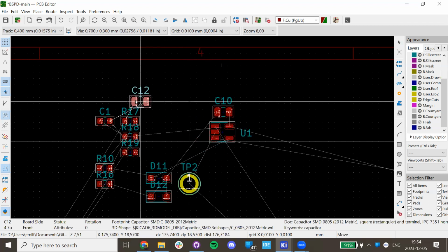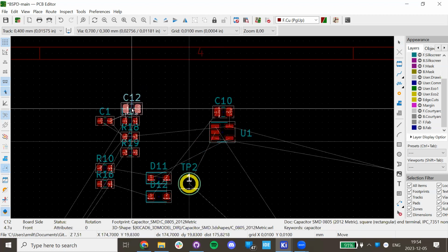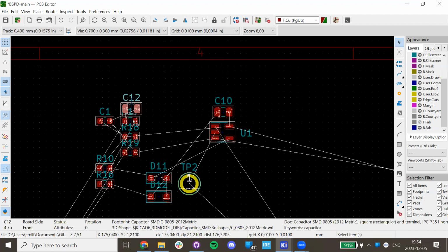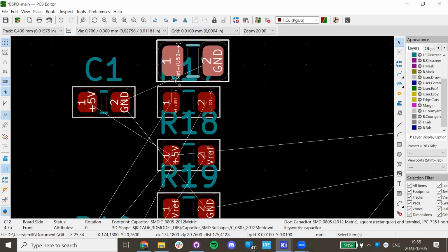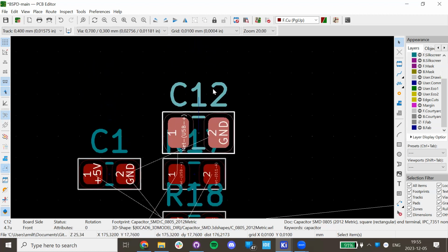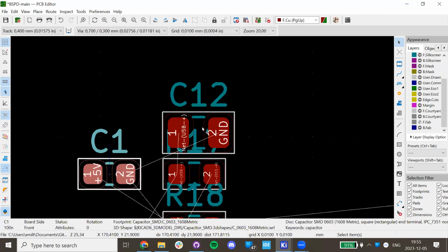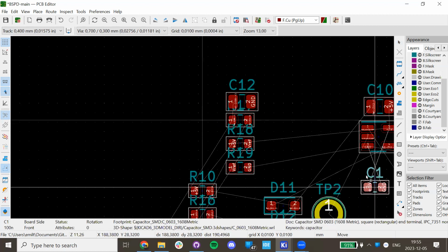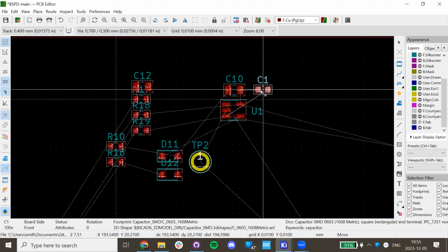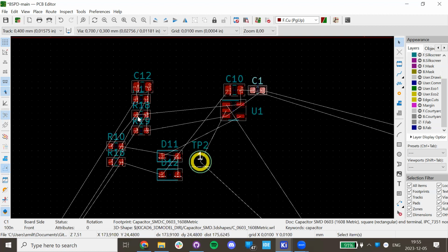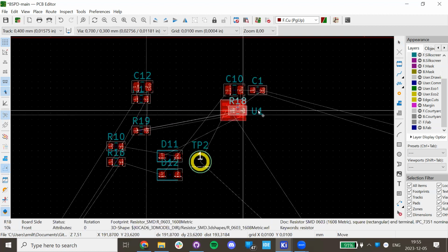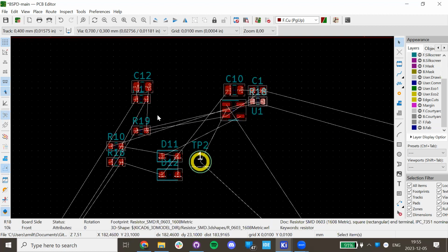Then you put on a lamp and a template that looks like your circuit, and shine on the copper, and the copper that is not masked will be hit by the light, so the photoresist will disappear more or less. And then you put it in an etching bath, which etches away the copper that is not covered by the photoresist anymore. So it chemically removes the copper that was exposed to the light.